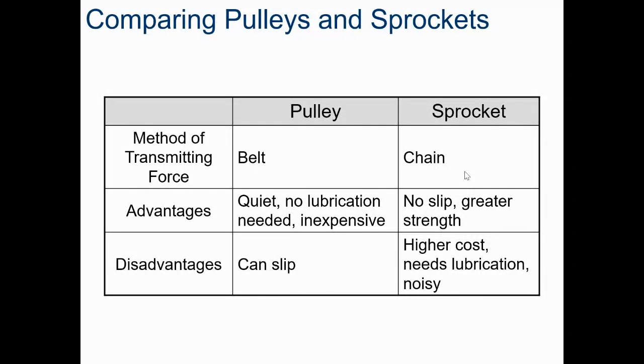And you can adjust that depending on what kind of material you're cutting. If I'm drilling something that's harder, maybe I need to go slower but have more torque. If I have a pretty light duty material, maybe I'm going to go fast and not as much torque. But it gives me the option to adjust it.